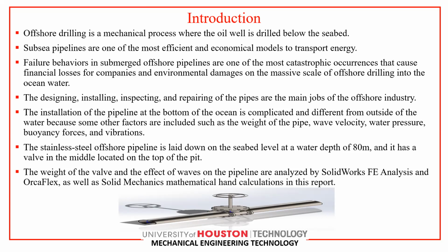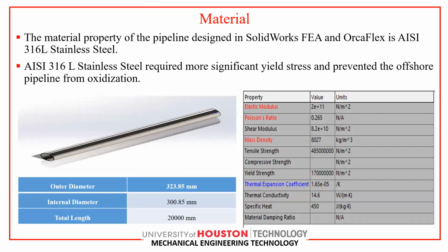Because when I design the valve, because of too many assembly parts, the software, SolidWorks, gets errors and doesn't work to give me the final result. That's the reason I applied the normal force to the middle of the pipe where the valve is located. And I use that value of the force from the OrcaFlex dynamic analysis software. So anyway, let's go to the next slide.